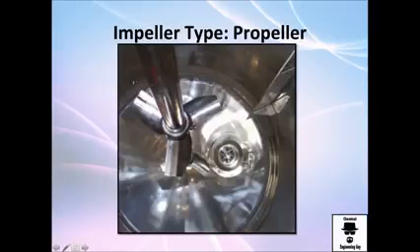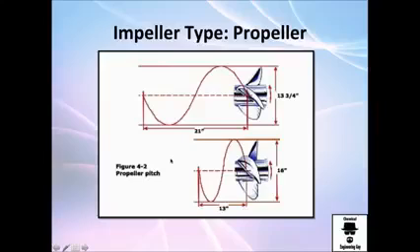Here you have the shaft, the vessel, the valve that closes and opens, and here's the outlet, and the impeller, which here is a propeller, and actually you have two. One, maybe this is 5 meters. Oh, here we have a baffle, and here's the other propeller. So we have 1, 2 here in order to improve the mixing. So how does it move? Well, it starts moving here, rotates, and what you're going to generate is this type of flow.